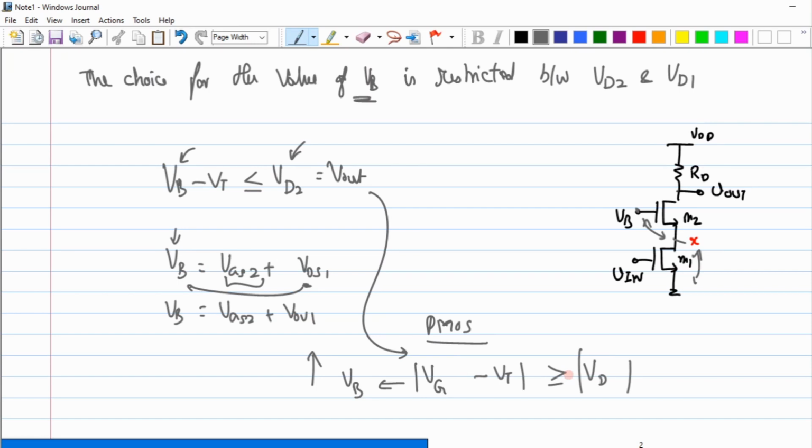Okay. So now, how would we build it? I got an idea, but I need a circuit out of it, right? So how do we do that? Did you really understand the main problem with the cascode amplifier? I have a value of VB that cannot go up just because this guy is hitting me. I cannot step down just because the VDS is defining me a minimum value here. So it's been stuck between both these constraints.